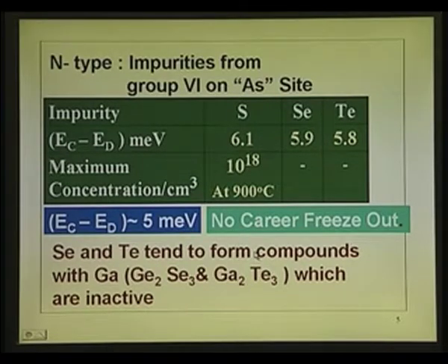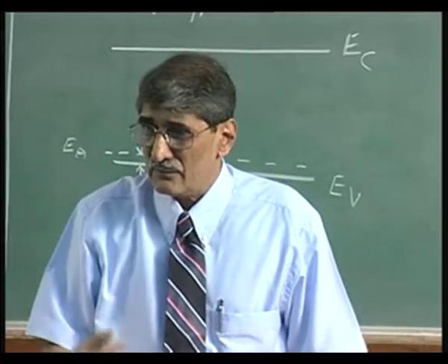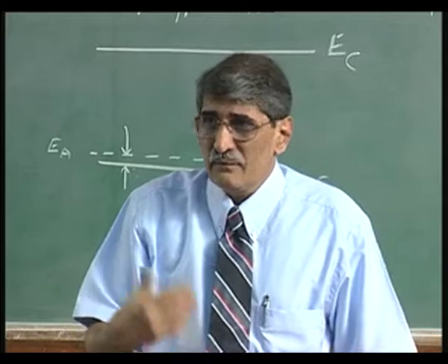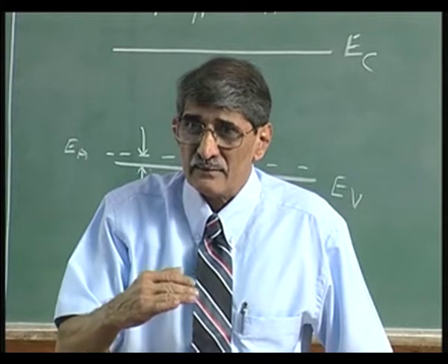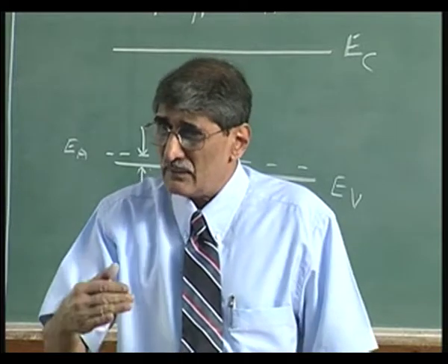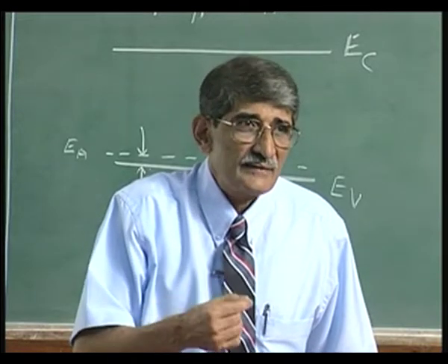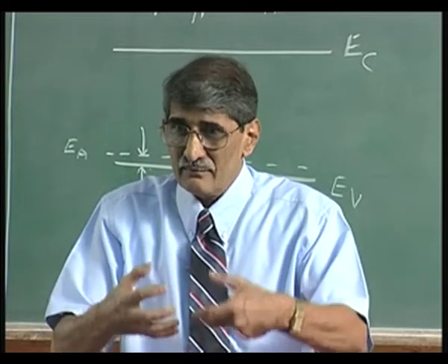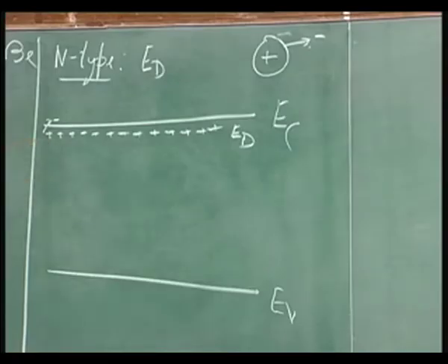If you take silicon, for example, it requires a certain energy of 50 milli electron volts for donating the electrons. As you go down in temperature below room temperature, as you would have calculated in some places, the number of donors which are ionized decreases. You go to much lower temperatures, fewer and fewer of them are donated. What does it mean? That means the electron concentration goes down; it is frozen into the donor atom itself. It is not moving, it is right here. That is what we imply when we say it is frozen.